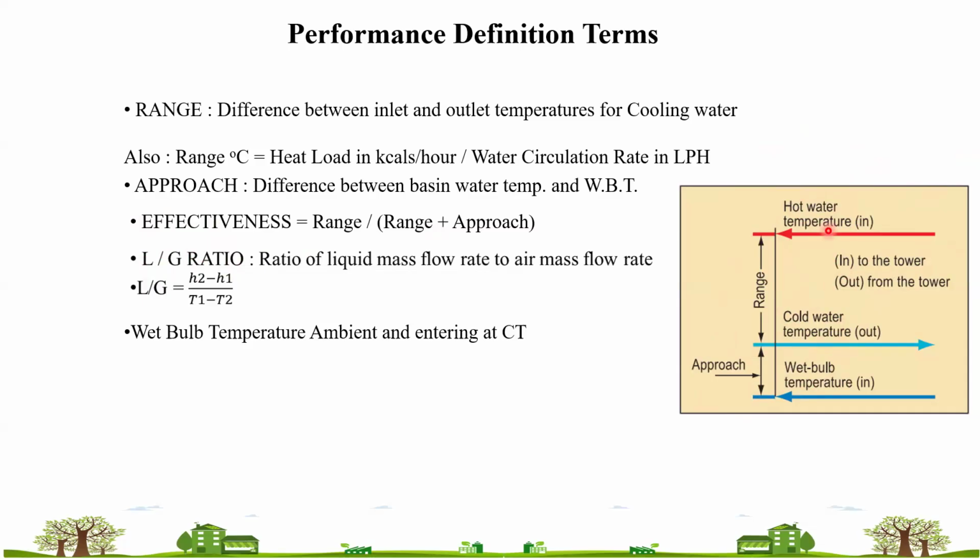How is the air quantity calculated in that case? You can calculate it with the help of an anemometer at the exhaust or inlet. One methodology is that. Then you can calculate it with the help of whatever data of that particular fan is available with you. These fans are defined in terms of meter cube per hour, and your water flow is also around meter cube per hour. So you have to measure that air quantity.